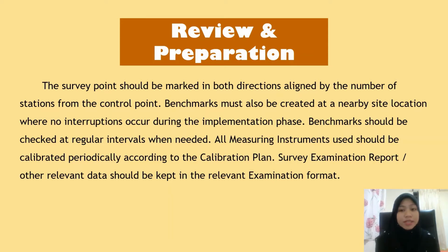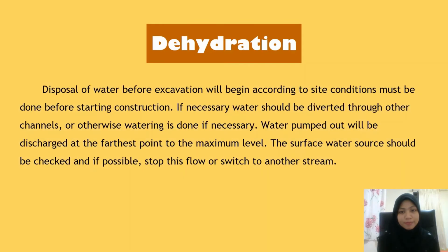All measuring instruments used should be calibrated periodically according to the calibration plan. Survey, examination reports, or other relevant data should be kept in the relevant examination format. The second one is dehydration. As mentioned before, the construction site of the culvert must be dry.